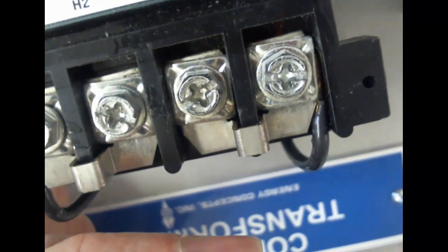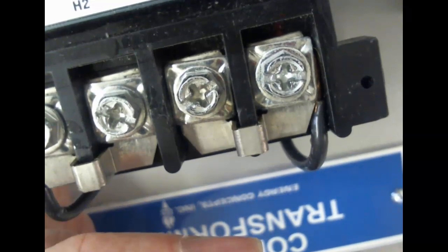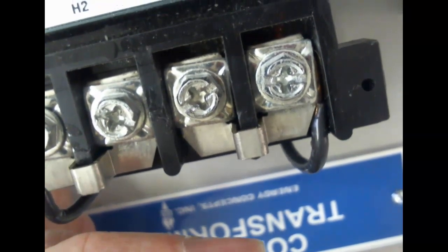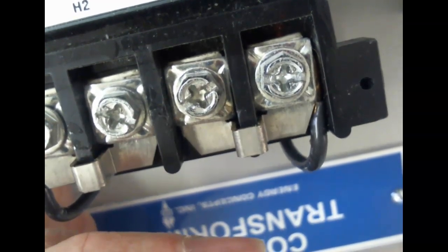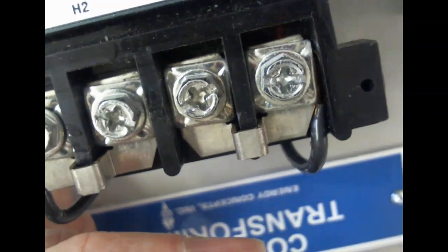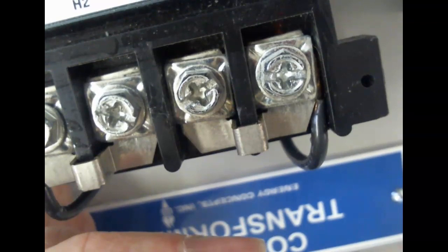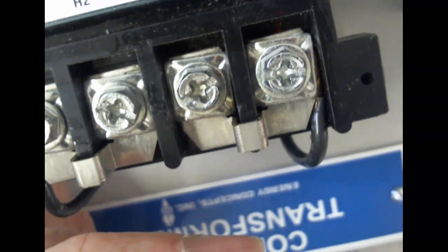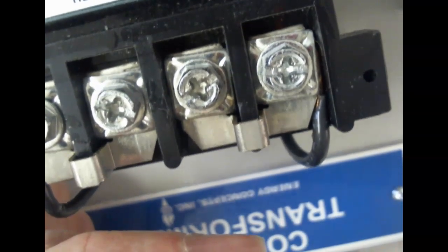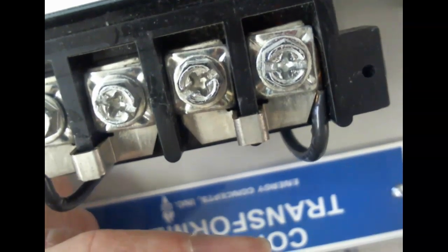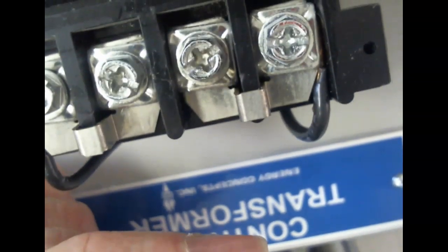So to get your low division ratio, we're going to hook the primaries up in parallel. To get the high ratio, you understand, we're going to hook them up in what? Series. Because now the primary voltage is going up, which means the current flow in the primary is going to go down. You understand that this is not Ohm's law. We're talking about the source. Now, you're right, on Ohm's law, if I put more voltage on a circuit, the current in the circuit goes up, but we're not talking about the load. We're talking about what we're doing with sources.